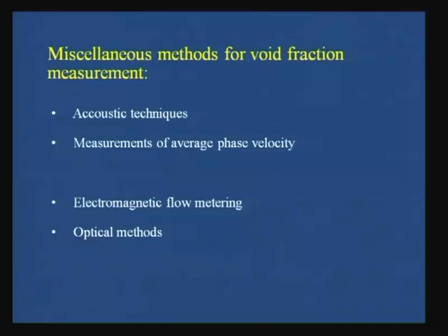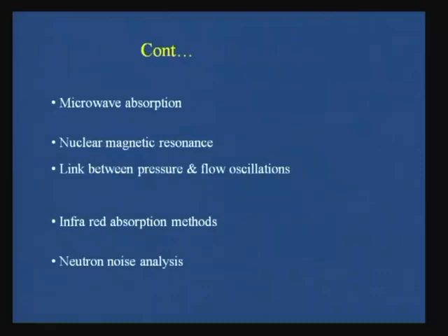Then definitely measurement of average void fraction either by radioactive tracer or electromagnetic flow metering devices. Then there are other radiation absorption techniques which can be microwave absorption, infrared absorption, nuclear magnetic resonance, neutron noise analysis, and so on and so forth.